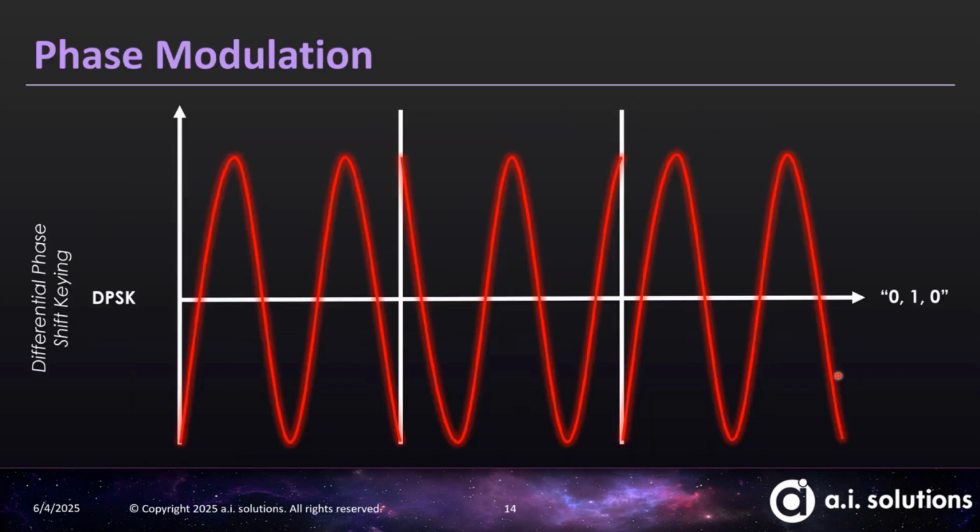So amplitude modulation isn't the only story, although we don't get too complicated with the wave properties of light. Like I said, in general, things are kept pretty simple in terms of modulation in optical comms. But one you will see occasionally is something called differential phase shift keying, which is basically this: instead of messing with the amplitude, we're going to change the phase of our signal. So what we'll basically do is say one phase corresponds to a 1, and then a phase that's off by pi or 180 degrees, that's going to be a 0.